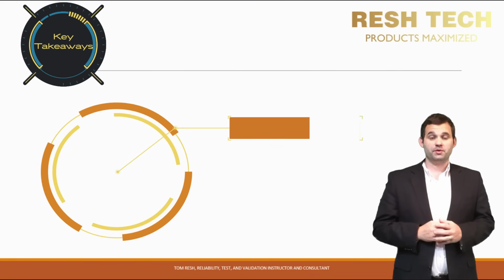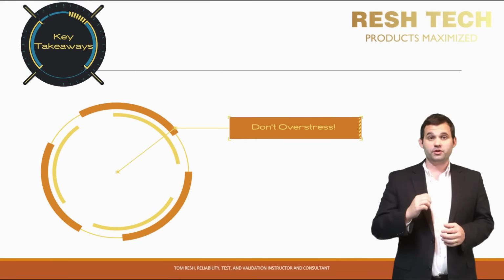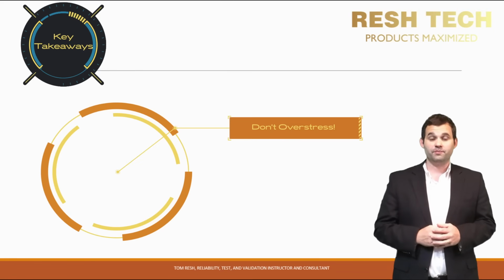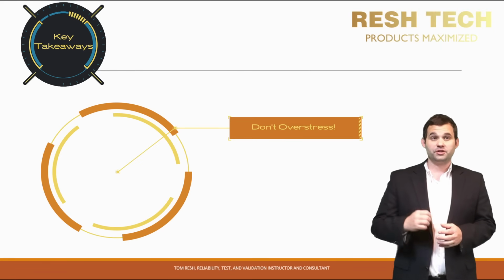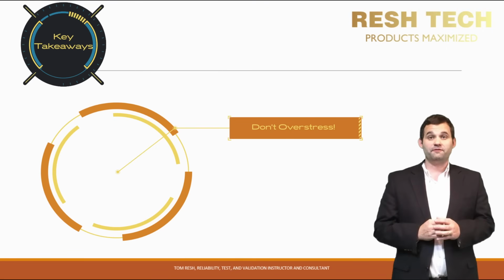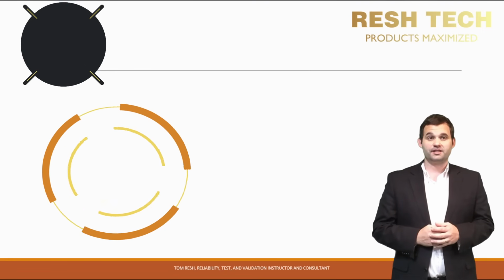Don't get carried away with acceleration factors. Make sure you do not increase stress levels to the point that you produce failure modes that you would never see with your product in the field. For instance, you do not want a part to turn into a pile of dust because you created stress levels that would be worthy of qualifying a component for a rocket when you are just testing a consumer product.